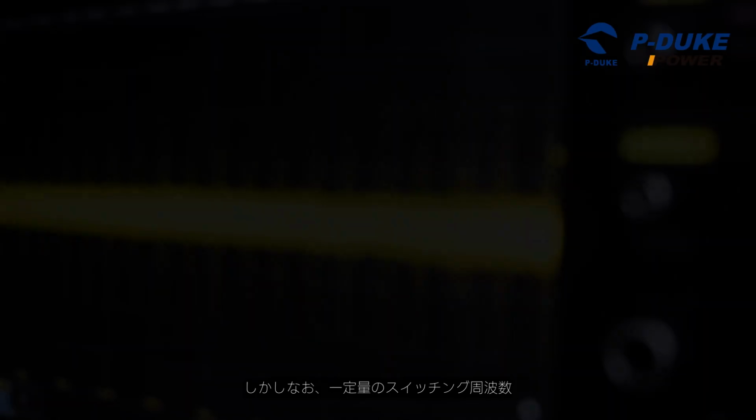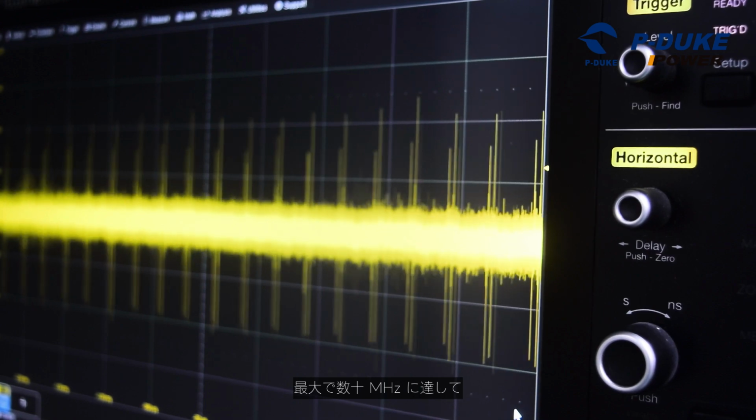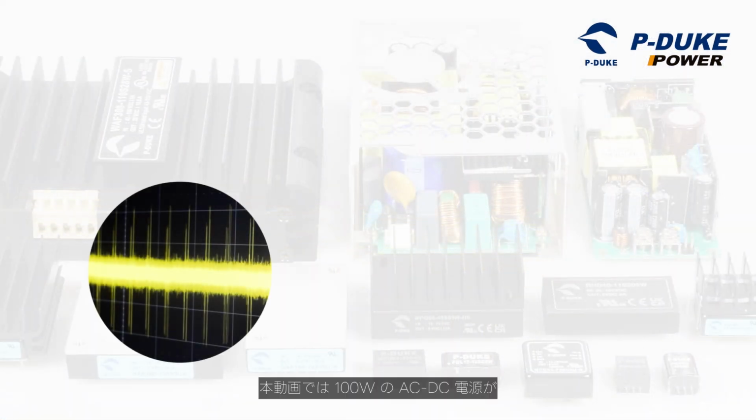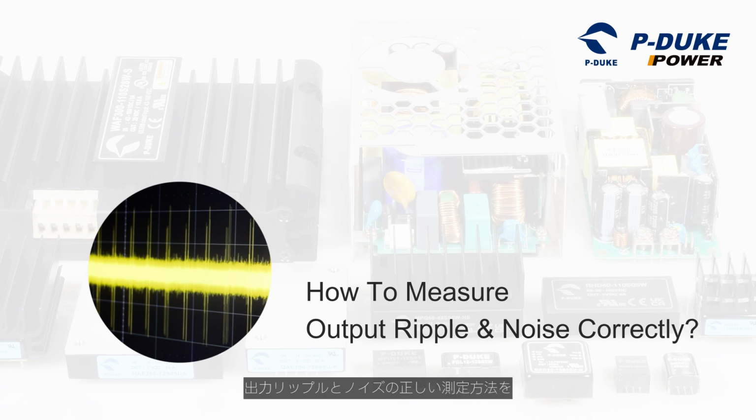However, a certain amount of switching frequency ripple and high-frequency noise up to several tens of megahertz remain at the output. This video describes how ripple and noise are measured correctly at the output of a 100 watt AC to DC power supply with a resistive load of 60 watt.